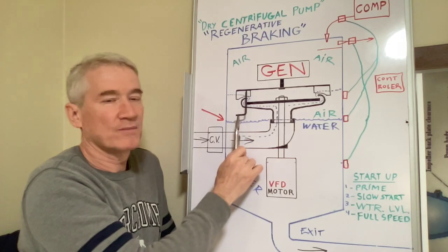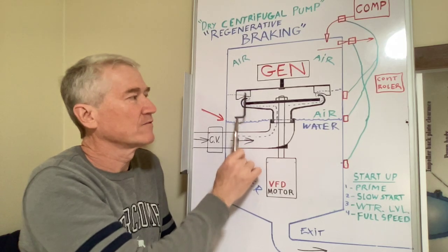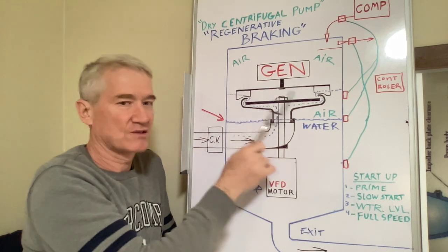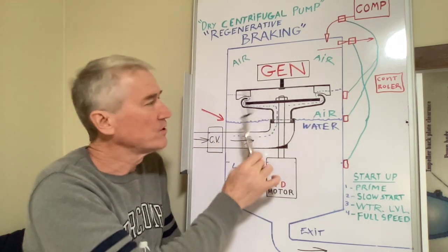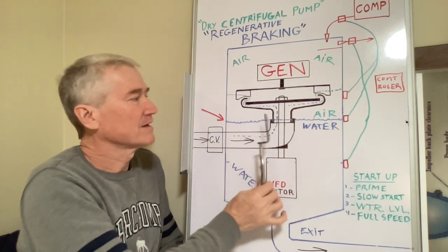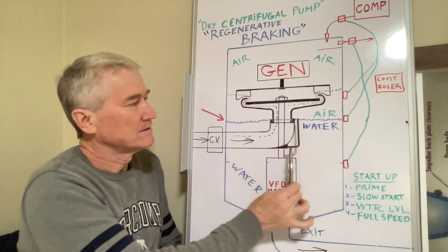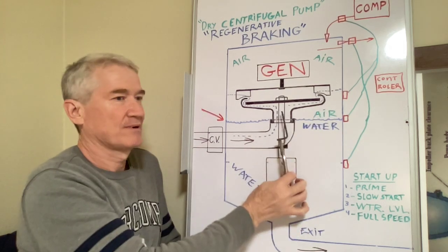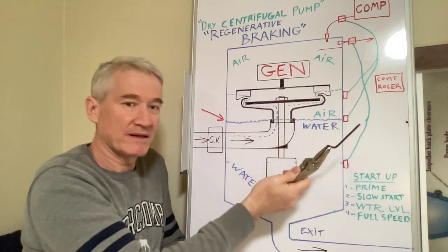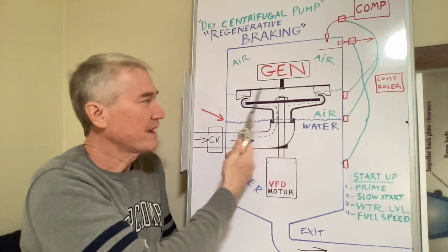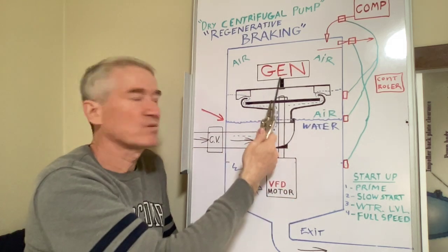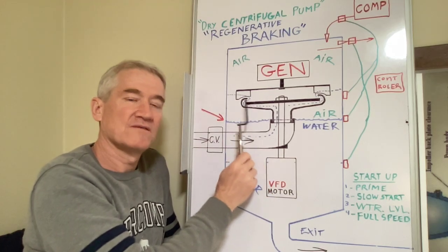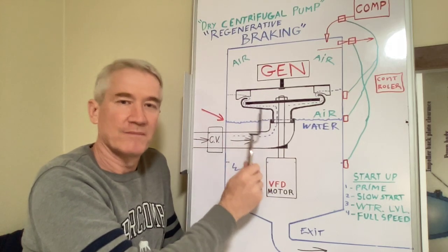And as your turbine catches the water coming out of the impeller, it would also be dragging on all that slow moving water around it. So when the housing has air at the top, well, that changes it completely. Now you can use a turbine and you can regenerate some of that energy from the velocity of the water coming out of the impeller.